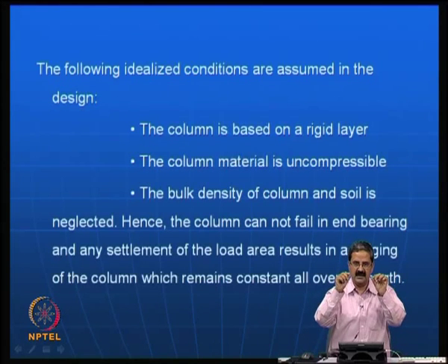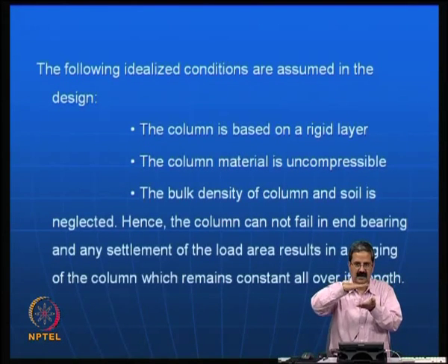Actually what we assume is that there is a small bulging which is constant in the field. But we know that in the field there are bulging differences, it depends on the overburden of the soil. So, actually we develop a simple method, understand its limitations and make corrections for it. This is what Priebe's method is: it is an elastic method, because it only uses a deformation modulus.